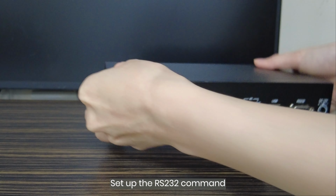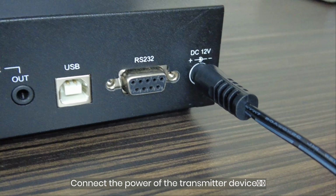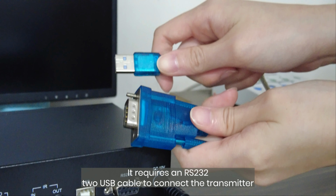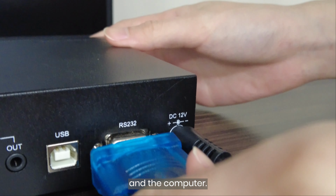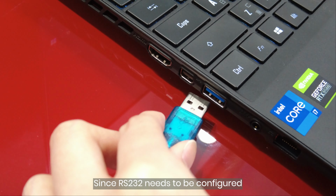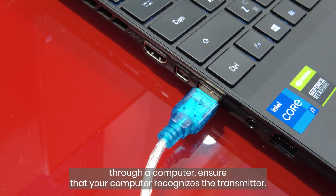Set up via RS-232 commands. Connect the power of the transmitter device. Setup via RS-232 commands requires an RS-232 to USB cable to connect the transmitter and the computer. Since RS-232 needs to be configured through a computer, ensure that your computer recognizes the transmitter.